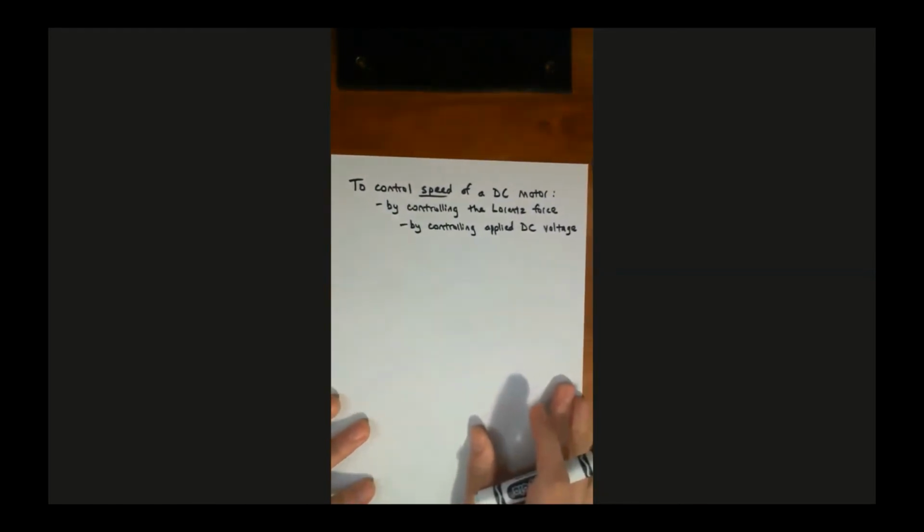So we can already say something about the transients that we're going to talk about next time. If I've got a DC motor and it's running along at normal operating speed at 6 volts, and then all of a sudden I apply 12 volts to that DC motor, it's going to result in more current through the armature, and that's going to result in a larger Lorentz force, and that's going to result in a larger torque that's applied, a larger motor torque, and that's going to result in acceleration of the motor and ultimately a faster speed of rotation of the motor.